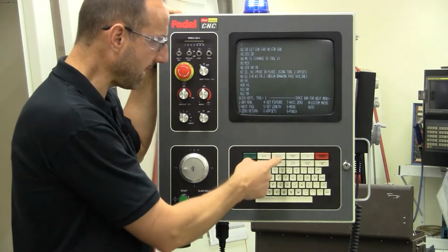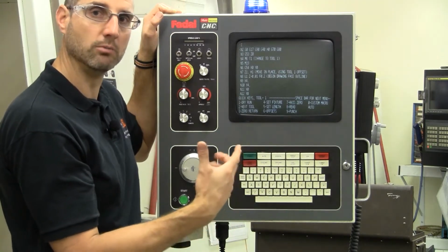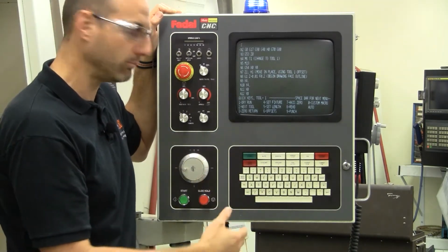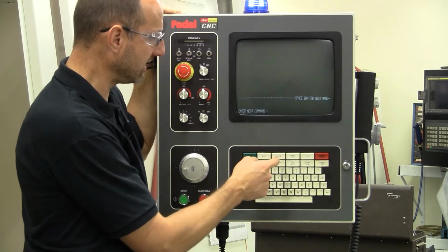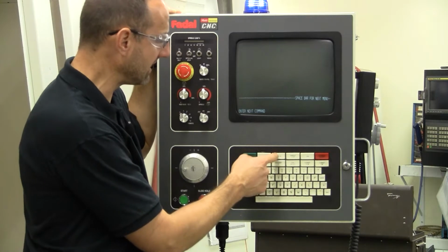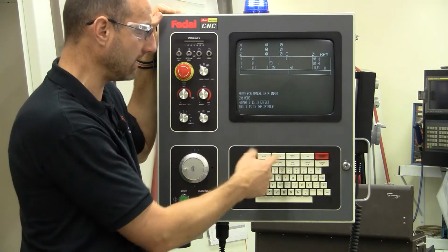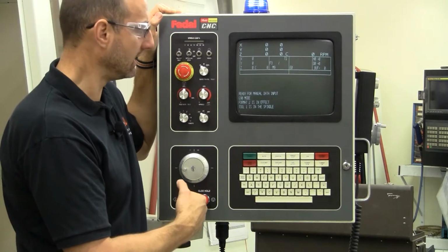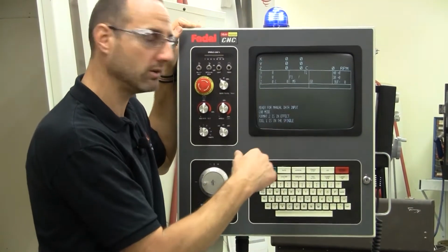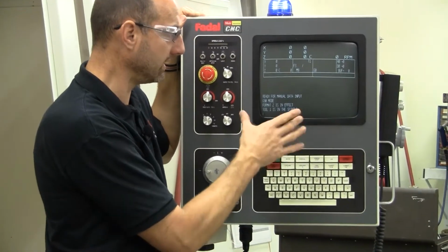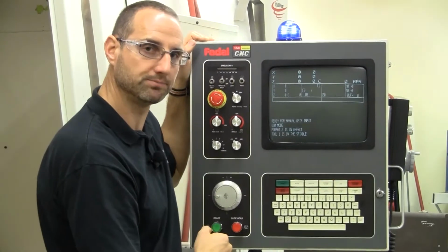Now, the manual key in and of itself is intended to allow you to get into a mode known as manual data input, or MDI mode. I can do that by cycling the manual key until I enter into the MDI mode. So here I did it. I had to push it twice in that case to exit me out of the program edit mode, essentially, and then the enter next command prompt. And now I'm in manual data input mode.